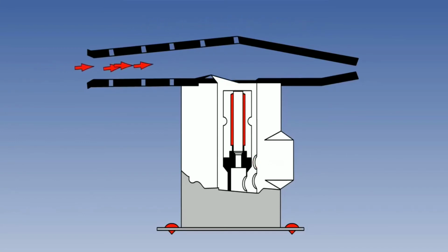Flow separation is achieved because water or solid particles have sufficient kinetic energy to pass directly through the air intake and exit. The bleed holes we can see in the intake casing allow the higher pressure air escaping from within the intake casing to draw off boundary layer air. An integral heating element prevents the formation of ice. The effect of the heating element on the temperature sensed is small and is not significant.